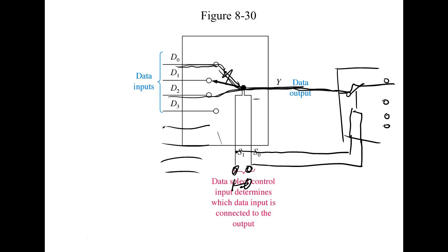So on time domain multiplexing, the advantage of these multiplexers is you can send information, but on fewer wires. But what that's going to do is limit your speeds, right? You understand that? Because if I'm constantly switching between them to save this time, then you can't get the speed. So the more you put on that single wire, the less bandwidth each one of them is going to get. Right? They're going to get the same bandwidth when they're on there.